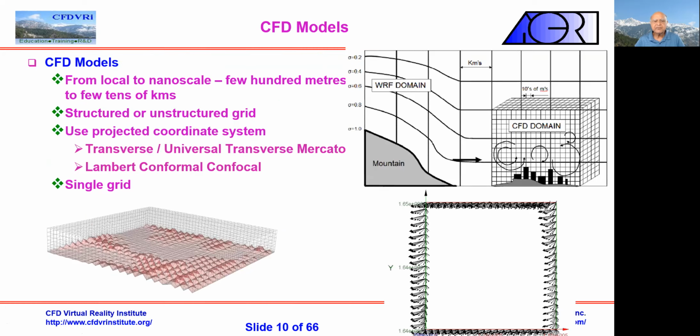and all that. Now, when we come to the CFD models, they are useful at a smaller scale, at scales of 100-meter range, anywhere from a meter to 100-meter range. There are quite a few of them, right? Okay, or any CFD model basically can be used for that, okay? So what you typically do is you embed this model within the WRF in this case, within the mesoscale model, such as MM5 WRF, right? So then you extract the boundary conditions for that, and you put those boundary conditions into this model to drive